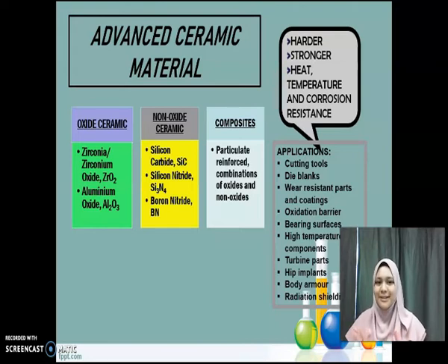The main difference between traditional ceramic and advanced ceramic is the material. Mainly, traditional ceramic is made out of what material? Clay. Advanced ceramic is made mostly out of oxide, nitride, boride, and carbide. Other than that, the difference is the process. Traditional ceramic is easier to make and we can shape it by hand, for example a plant vase, whereas with advanced ceramic we can engineer the chemical composition and crystal structure however we want.